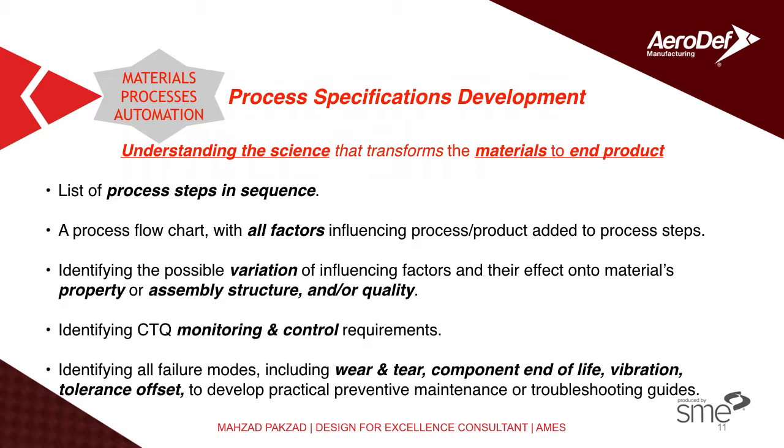So when we check these variations and their influence on the component, we have to check everything all the way to the end of the final assembly to make sure it's okay. We know we have got the component variation, tolerance variation, within acceptable range for everything, for the process that makes the component as well as for the end product.